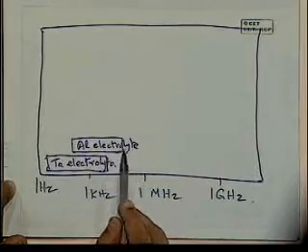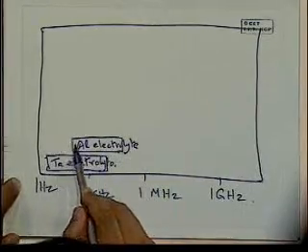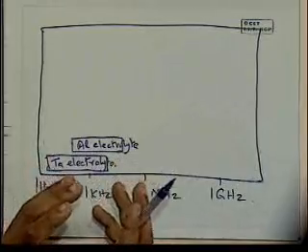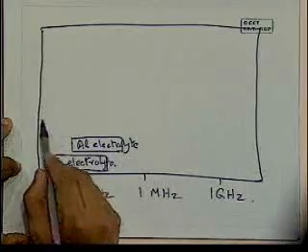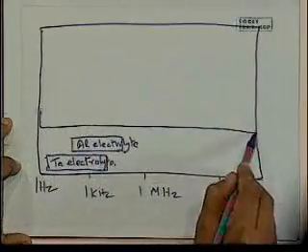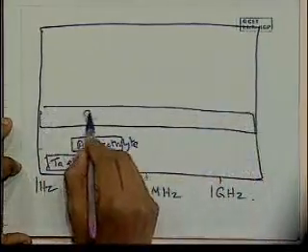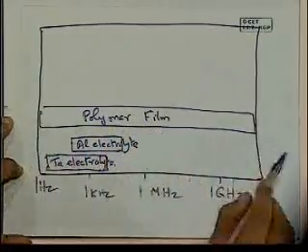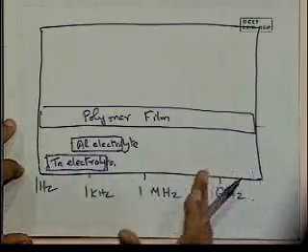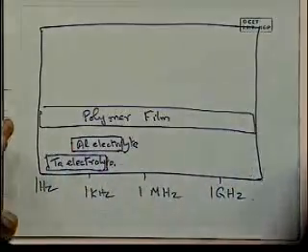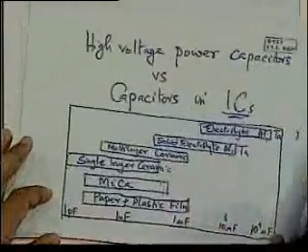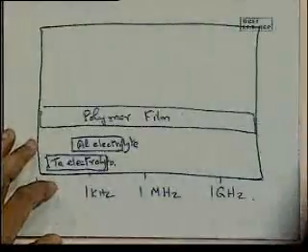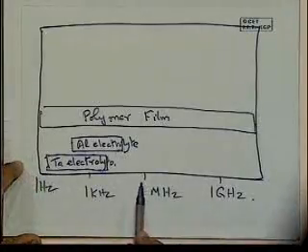Now remember, the different mechanisms, polarization mechanisms that we studied are responsible. How does this material function as a capacitor? How are the dipoles created? How is charge stored? That's what is determining the range of the use that we are concerned with. You can develop polymer film capacitors that pretty much go over the whole range. So in terms of the frequency of use, even though the range of capacitance that is achievable is relatively small, not so high capacitances, you can use it over a whole range of frequencies.